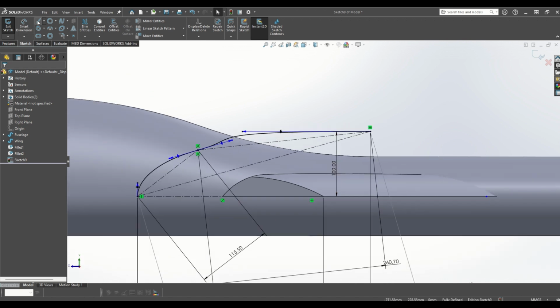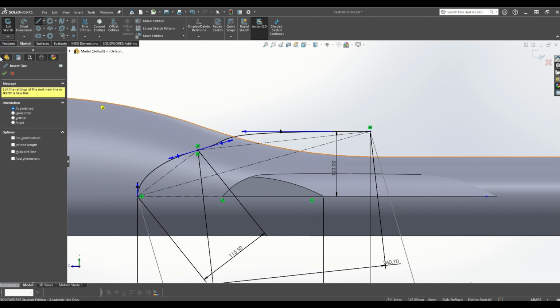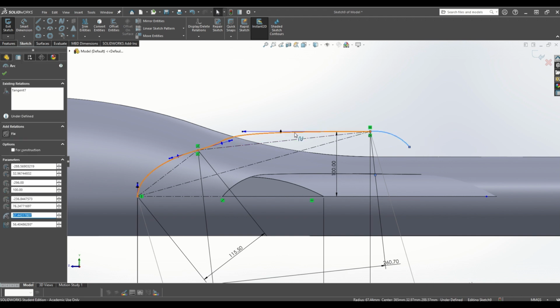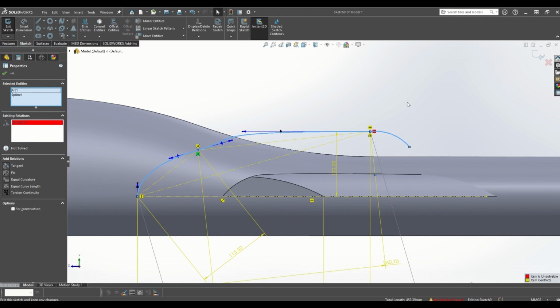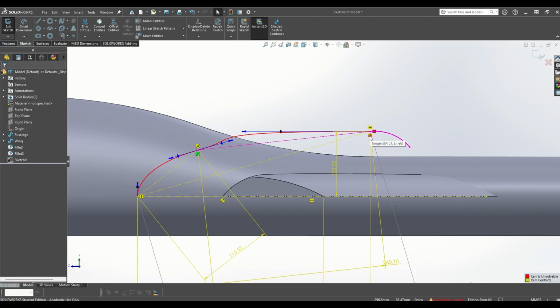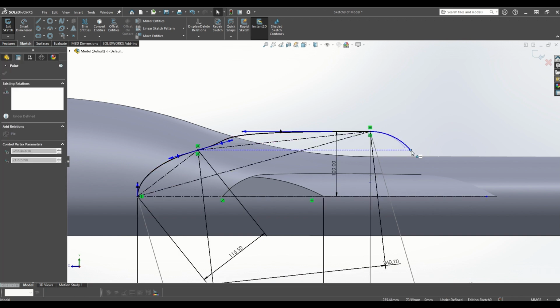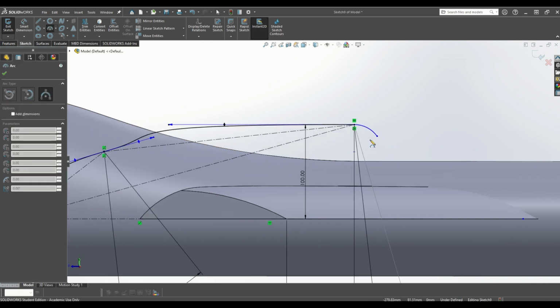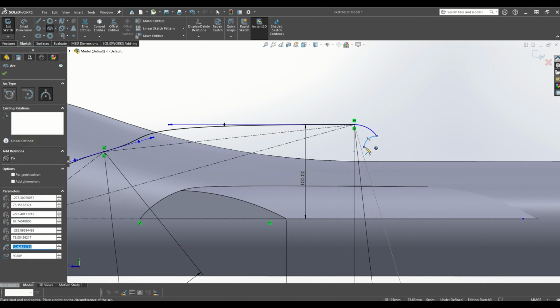And then I can just bring out a line to this. Maybe I might put in an arc back to this. I might go here like this and make it here like this, and then select the arc, select the spline, and say that I'm going to make these tangential so that there's an even flow to them. I'm going to delete that relationship that was added in unintentionally before this. So there, I'm going to have this arc around there, and then I'm going to have another arc, which is now going to be purely a visual thing for the nature of my flame that's coming out the back of it.